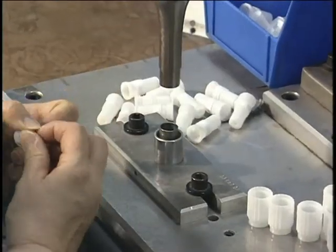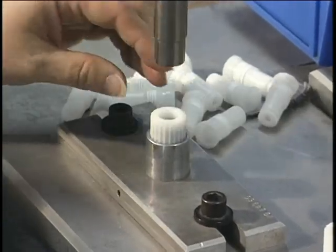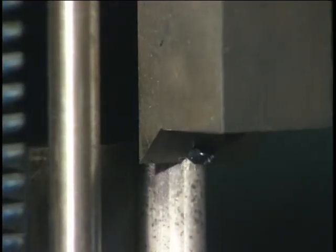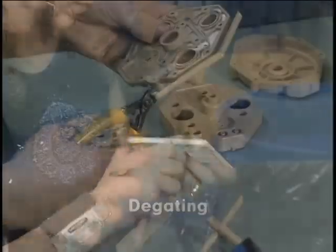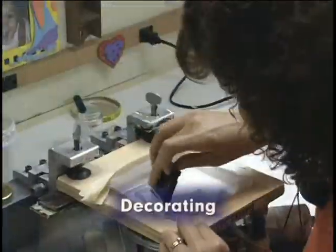Once molded, most parts require additional processing, such as assembly, for completion. But many plastics finishing processes are performed for aesthetic or appearance purposes. These finishing processes are the primary focus of this program and include degating, deflashing, cleaning, and decorating.